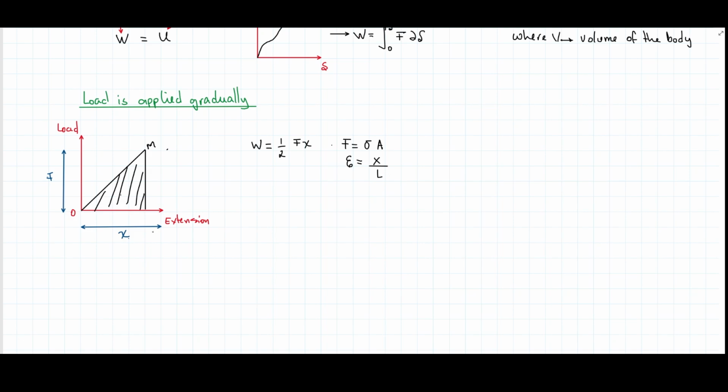So if we call that extension, you have an undeformed body, then you apply forces, and then it goes to the deformed configuration. Then that deformation is the extension. So when you compare that extension with respect to the original length, that's going to give you the strain. Now, definitely we're simplifying the case here because that might work, for example, for certain linear deformations. But it is also valid, and you're going to see that it's also valid for other scenarios.